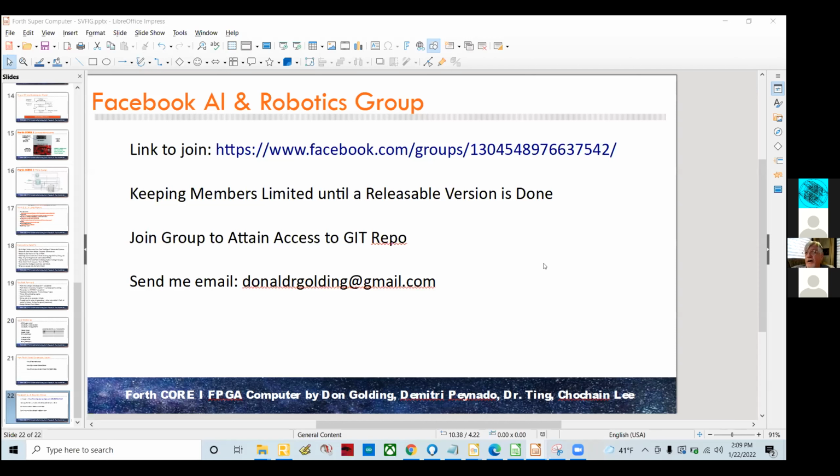We're not going for speed. We're not going for the smallest Forth processor on the planet. If you want a great processor, go use the J1. Great processor, 16-bit, totally different from the system you're describing. We're going more toward a CISC engine, but you can implement it on a $2 FPGA. I think he was asking about the RISC-V core, though. Yes, the RISC-V core can be boiled down to something like 800 LUTs, and the bit serial one is even smaller. Okay, yeah, we're using the Microsemi RISC-V.